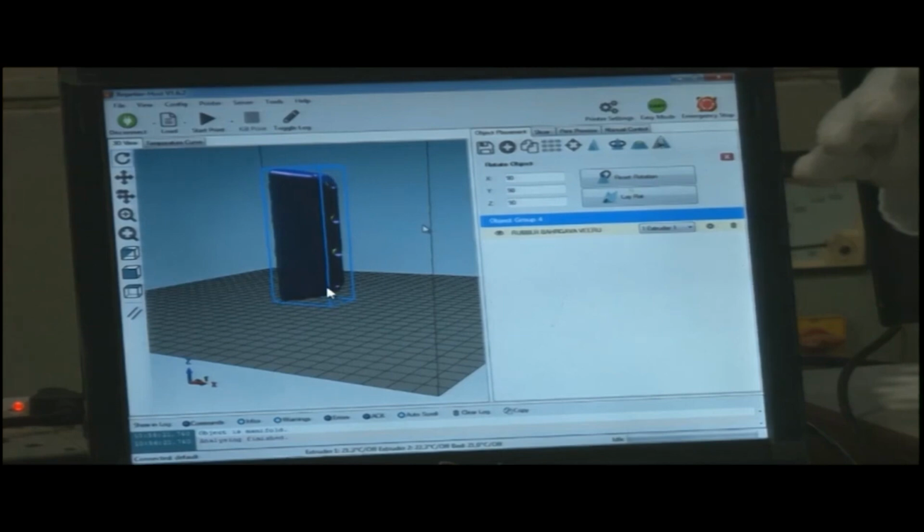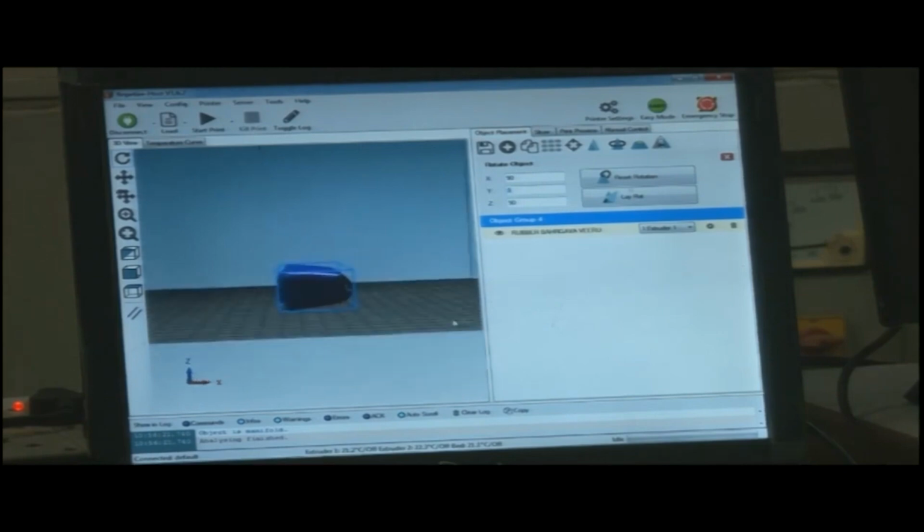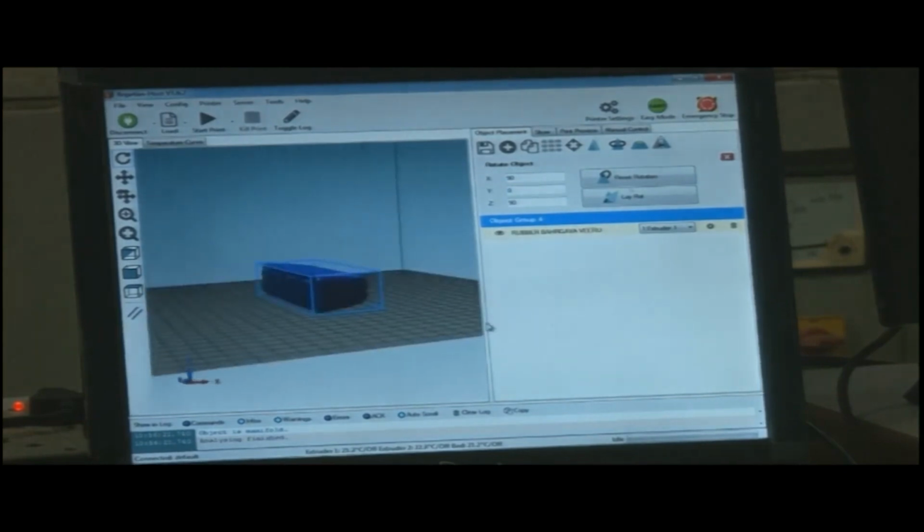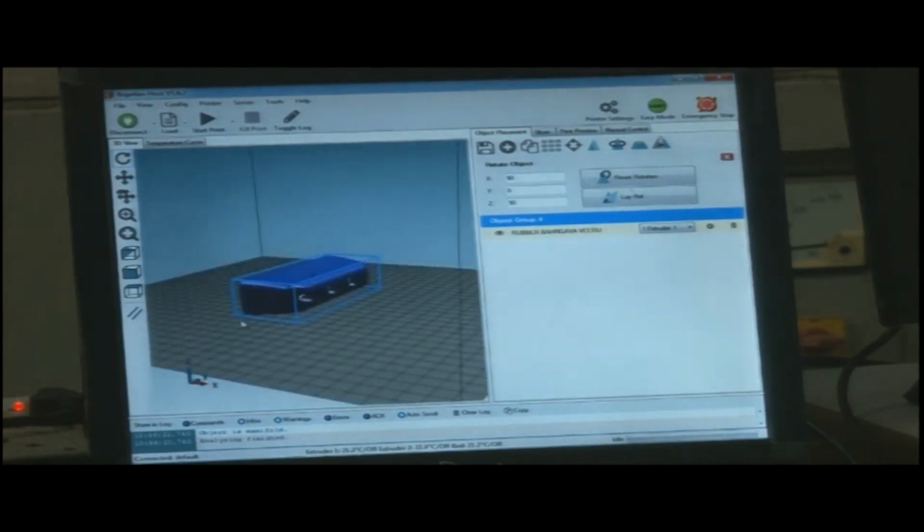These many layers are to be deposited, so the total time would increase. Total time means total cost of the product will also increase, because in the product cost function the machining time is one of its factors. So this is not a very good position to manufacture in. So we can opt to select the flat position and orient the job in the proper place and position.